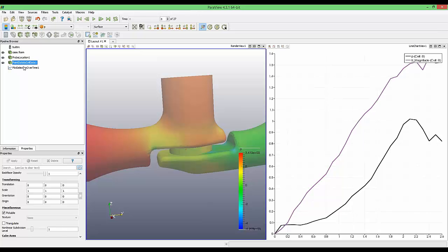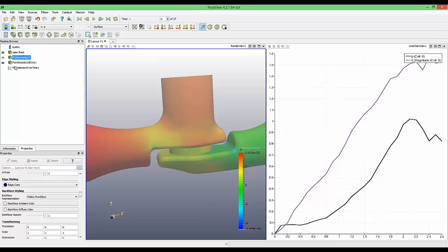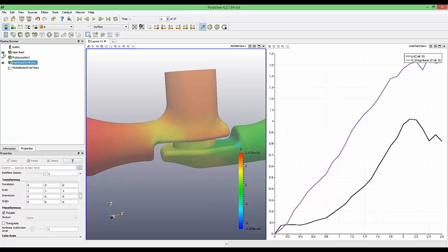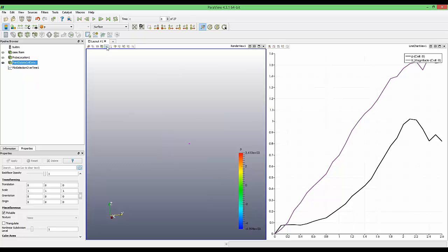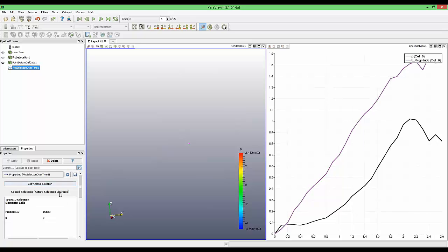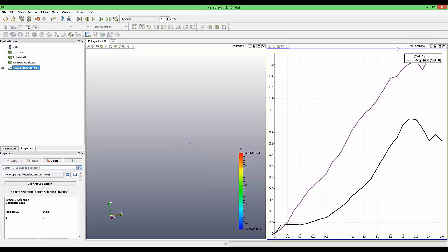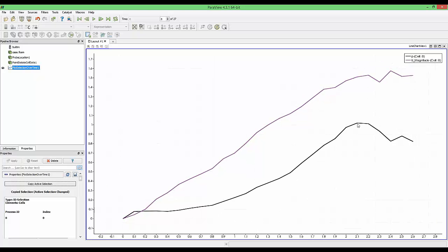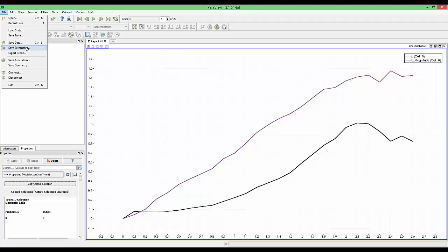And after that, when we have the point data to cell data filter applied to the probe, we once more choose select cells on, select the cell, and then apply the filter, that is the plot selection over time filter. After applying it, we will have this very nice plot of values, for example, velocity and cell and magnitude, which can be saved as a screenshot or saved as a data point.